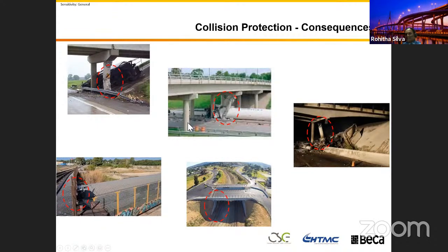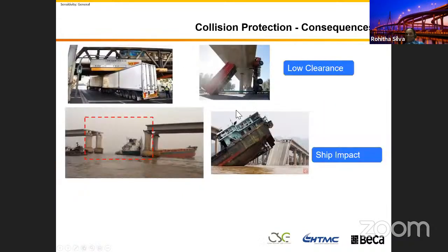That generates a significantly large force on your substructure, and it translates into your superstructure as well. Again, when you put in the lateral restraint block, it will help you distribute this load and control the movement of the substructure. I discussed this one in session 2 in detail.